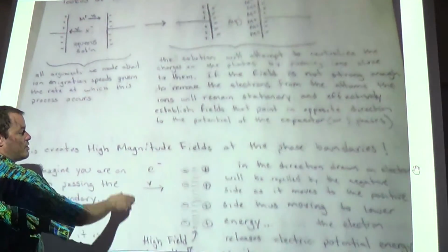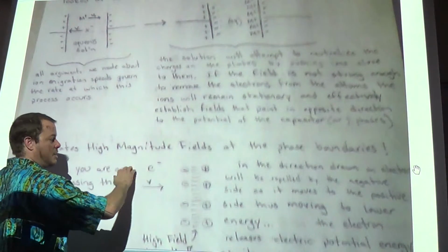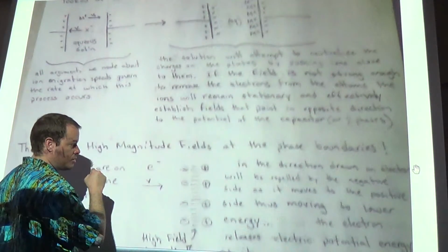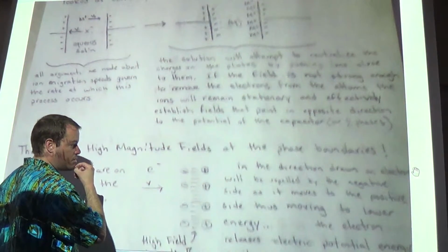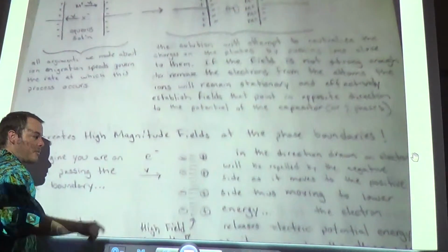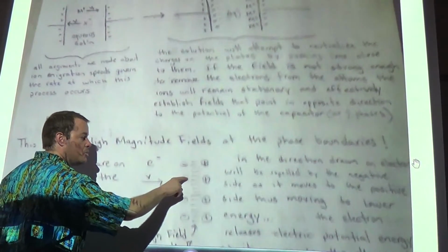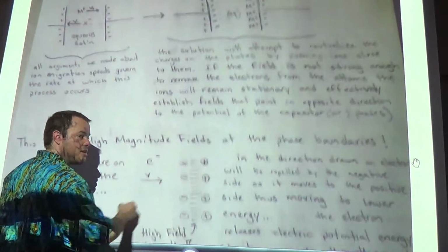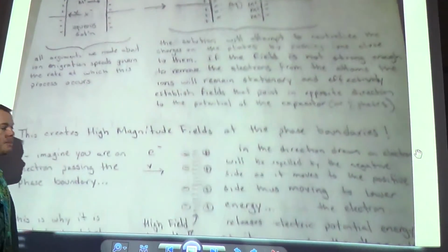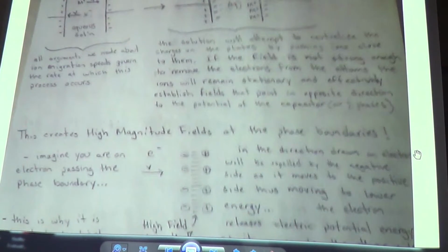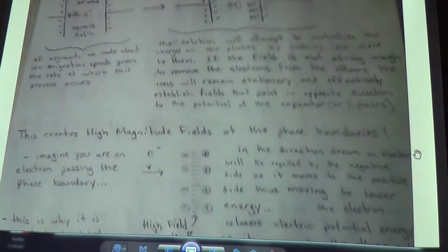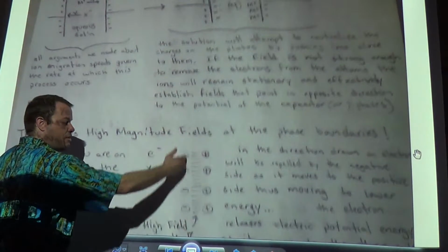I didn't draw this, but over here there's positive charge on the other side. Anyway, right across this boundary, when you begin to move from one side to the other, and you're an electron, let's say you get to right here, just to the interior, you're going to feel a really, really large push from all of the other negative charge that is present on this boundary.